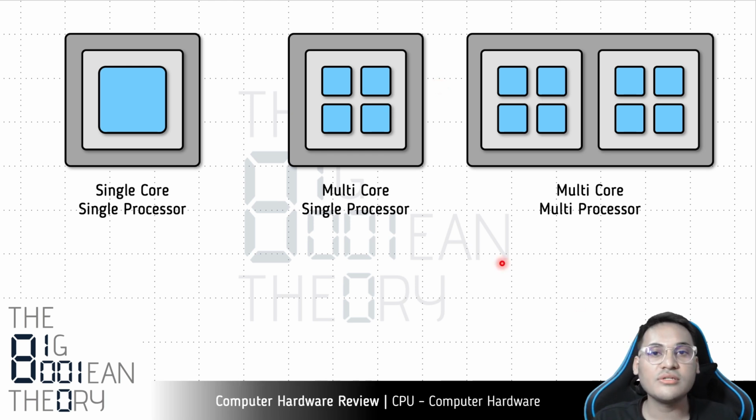So guys, this was it for this video. In this video, we talked about what a CPU does, what the major components in the CPU are, and how it works, basically the instruction execution cycle. Then we talked about an important concept, instruction set architecture, and finally some ideas on how we can optimize the performance of the CPU.